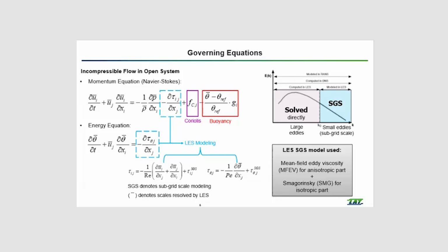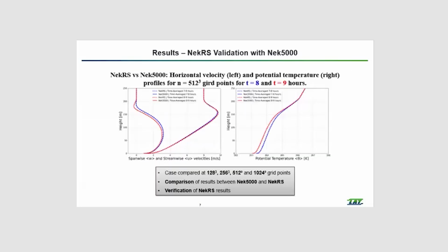And that's where the LES model that we used comes into play. We chose to use a mean field eddy viscosity model for the anisotropic part, and then the Smagorinsky model for the isotropic part of the SGS stresses.